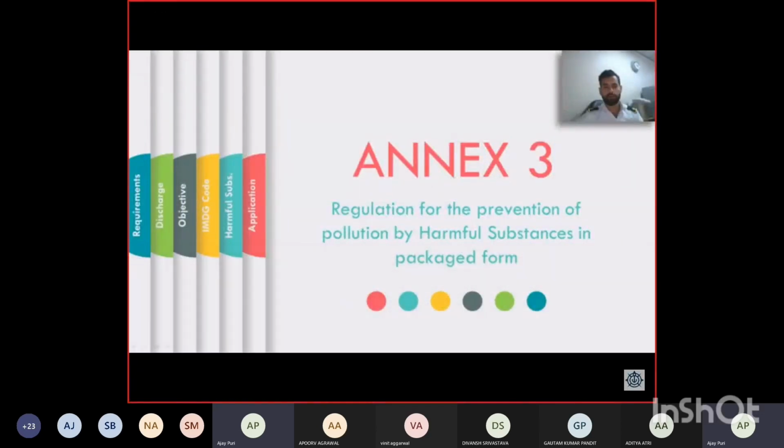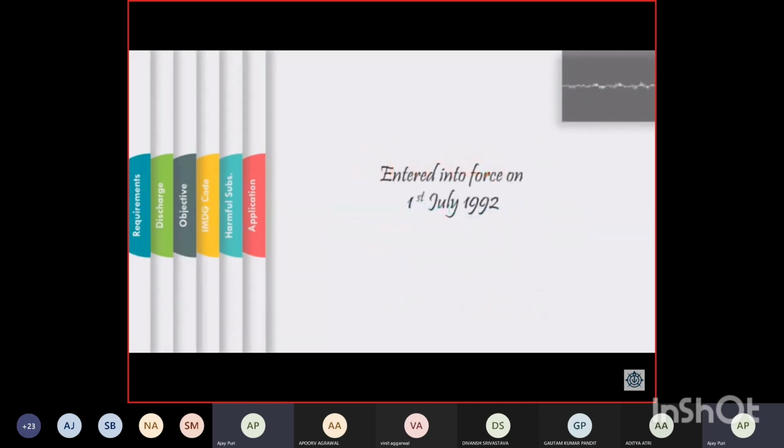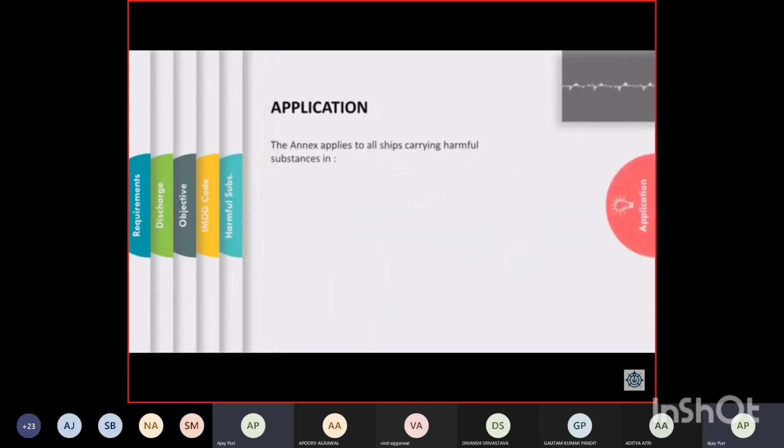Hello friends, I have received an overwhelming response from all of you for the videos of MARPOL Annex 1 and Annex 2, and a lot of requests to upload other annexes as well. In this video, we are going to discuss Annex 3 of MARPOL. So, let's get started. MARPOL Annex 3 is the regulation for the prevention of pollution by harmful substances carried in packaged form. Annex 3 entered into force on 1st of July 1992 and the revised Annex 3 entered into force in October 2010. First of all, let us understand to which ships Annex 3 applies.